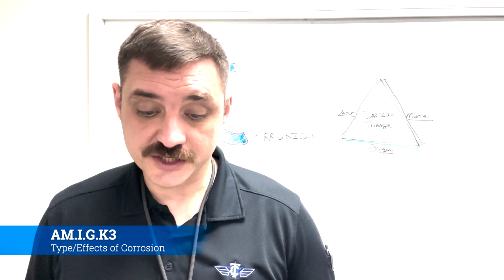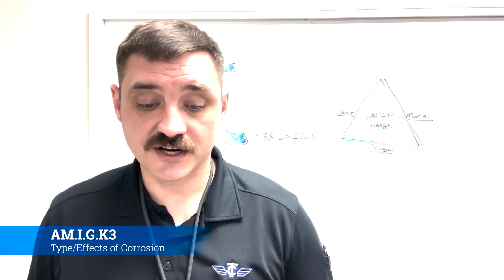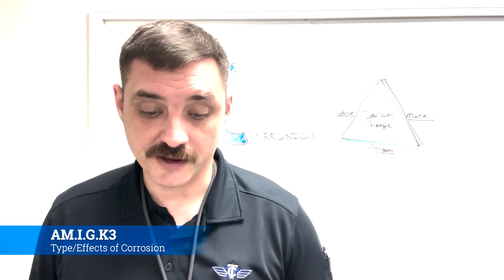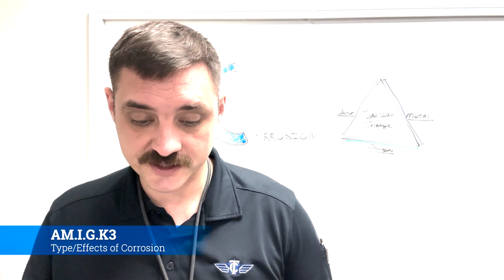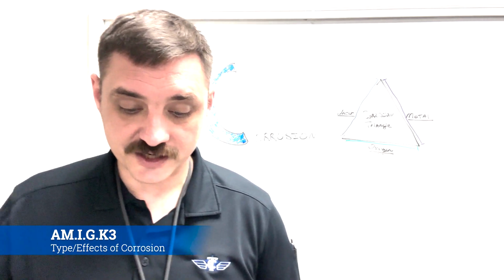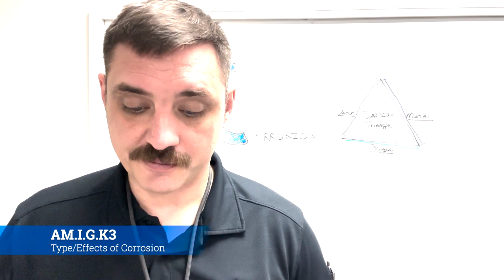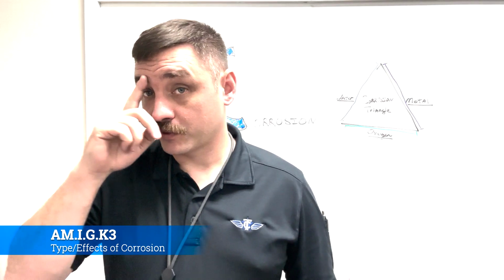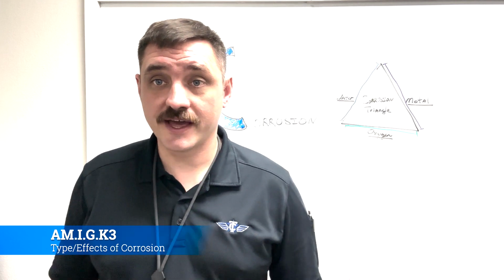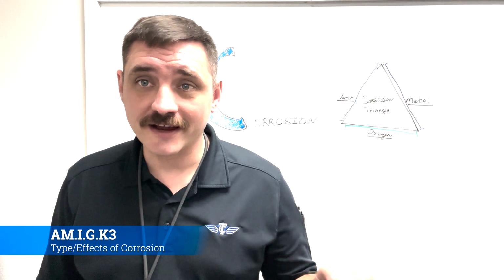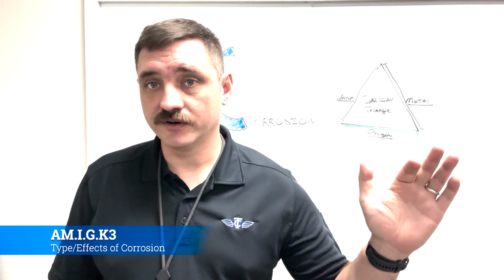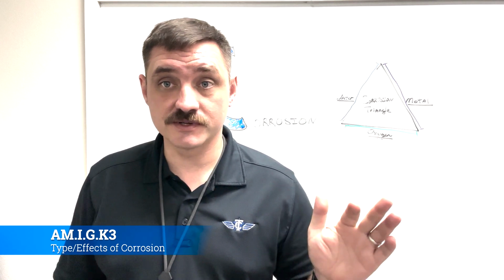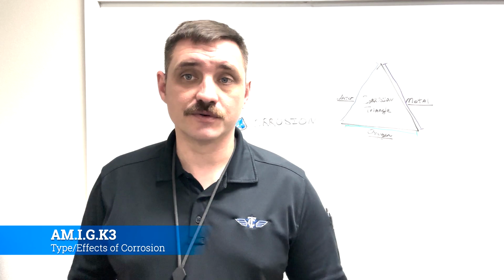All right, filiform corrosion. Filiform corrosion is a special form of oxygen concentration cell that occurs on metal surfaces having an organic coating system. It's recognized by its characteristic worm-like trace of corrosion products beneath the paint film. Okay, so filiform corrosion is corrosion that appears in a worm-like fashion. So you'll have a scratch on a piece of aluminum that exposes the metal to the air, and then corrosion starts to happen.